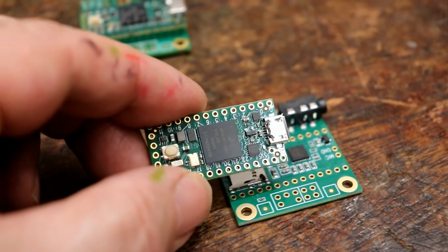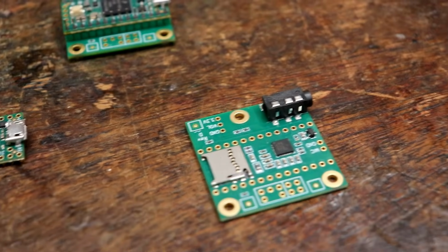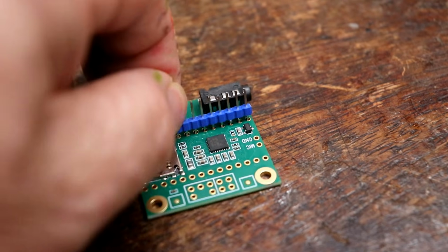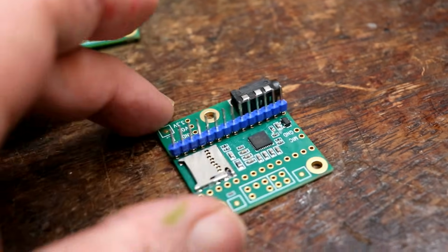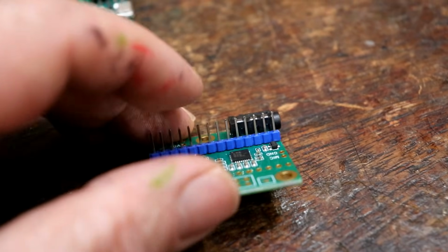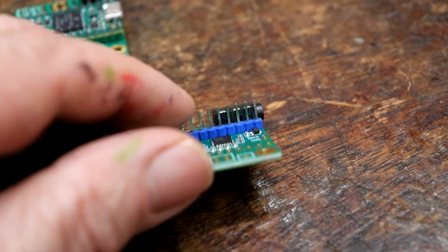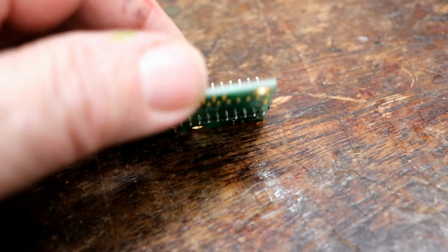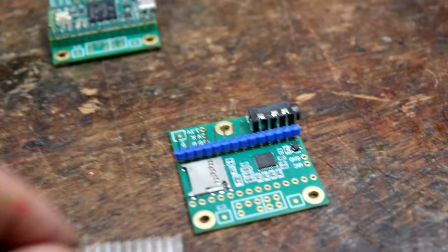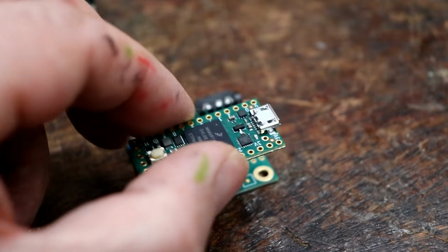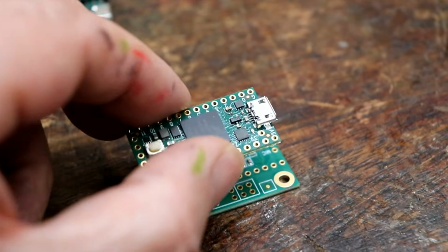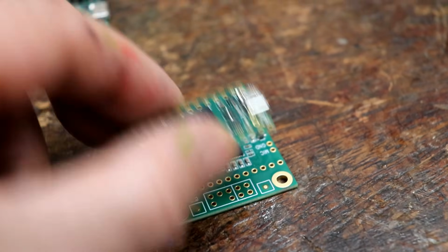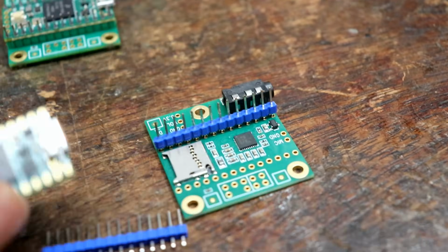It's amazing. So to join the two together, you just need 2 rows of 14 header pins, just the standard ones, having taken me a long time to realise how to fix the two together. Simply ridiculous. But they stick out far enough so that you can solder them onto the back. 2 rows of those, and then you can solder the Teensy on the top, just ensuring that the pin numbers line up properly. You don't get it upside down or the wrong way around.